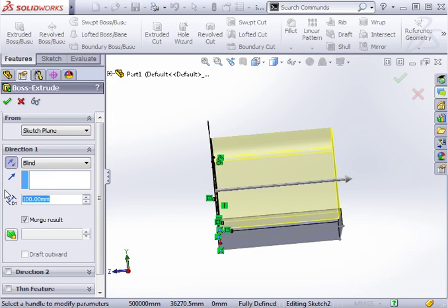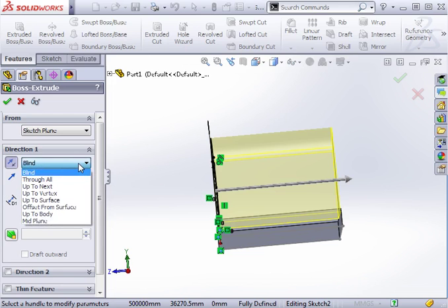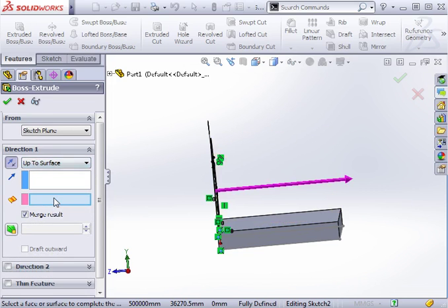To incorporate some additional design intent, taking advantage of the parametric capabilities in SOLIDWORKS, another approach would be to use an end condition. Instead of blind, another common end condition is the Up to Surface option. When you choose Up to Surface, you can see this box highlighted in blue appear, asking you to choose a face or a plane.